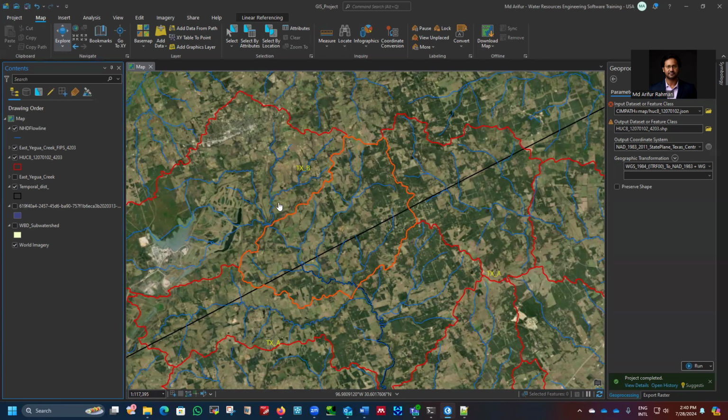We have different scripts to do that. If we need to, we'll explore together, no problem. I haven't even explored what data set we have, but if we find USGS, that's good. If we don't have USGS, we'll use regression analysis for this area, and I'll show you how to do that as well. So we'll calibrate after that, and we'll calibrate only for the 100-year, and then we can apply it to all the profiles. But I'm going to show you everything as a realistic project.